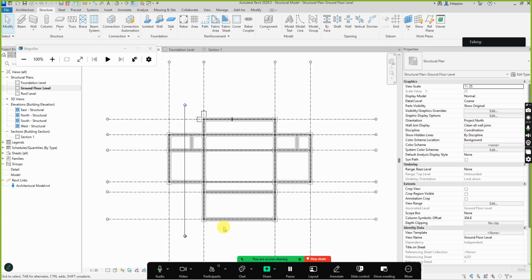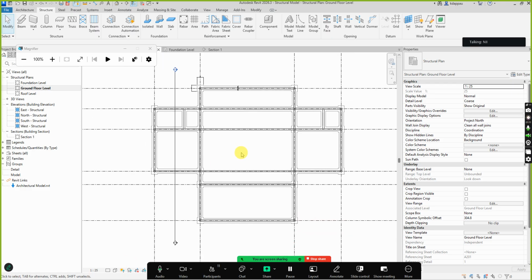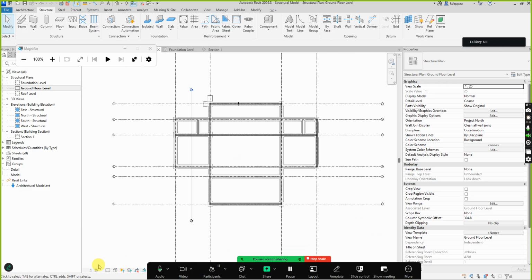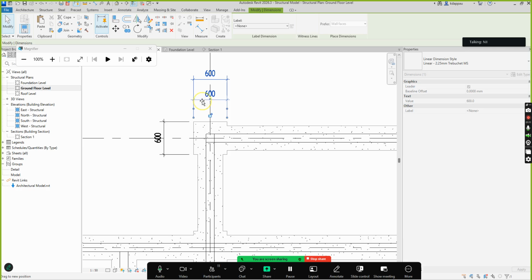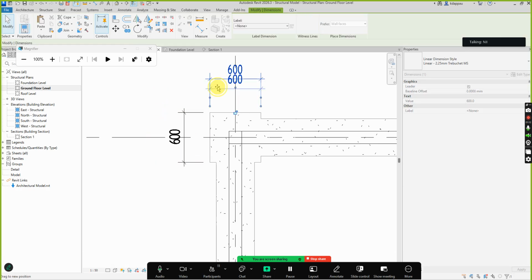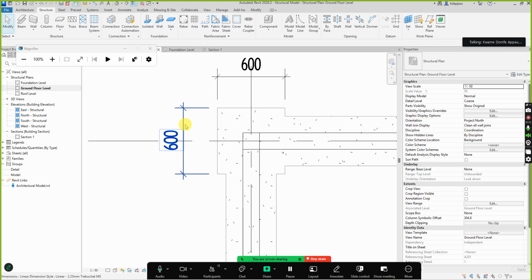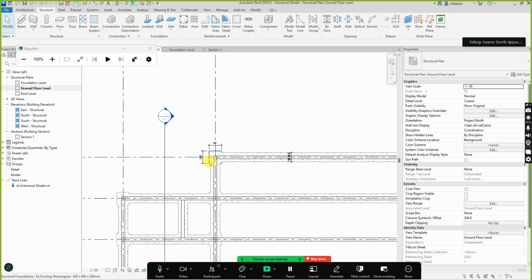Yes, please. I want to come in a little bit. If I can understand what Charity is saying, the 600 by 600 is because the building is single story. But if it's 2-story, 3-story, it depends upon the thickness of the column. It can be 900, it can be 1.2 or 1.5 or 1.8. It depends upon how tall the building is going.